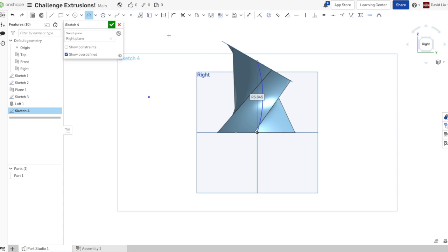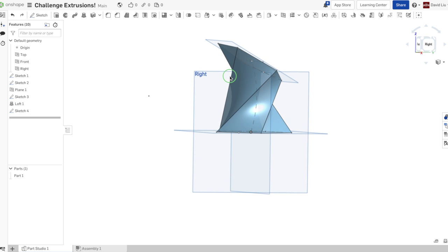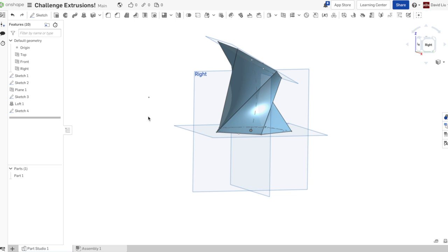Okay, so now we have our arc, and now it's time to make our path. Actually, before that, it's really important to do something else. Our current sketch, which is our path sketch, is below the loft. So some error might occur when you try to edit it, it will not appear. You're going to want to drag this sketch above the loft just like that to make sure that your loft 1 is below your sketch 4.